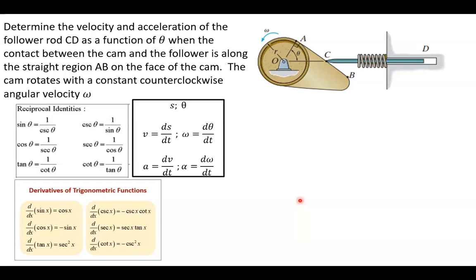So again, I brought these here, tried to put them into position as well as we could, and we're going to first look at how we can identify the displacement. We'll start off just up in this area. So if we look at this, we can try and get that displacement of OC, that distance from O to C, and make a relationship there as R over the cosine of theta.